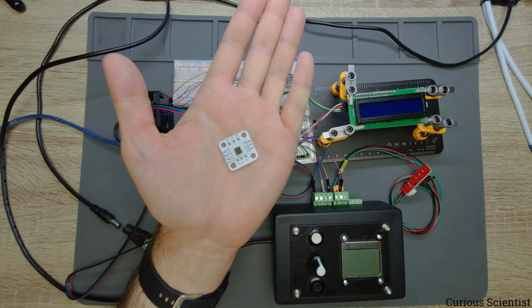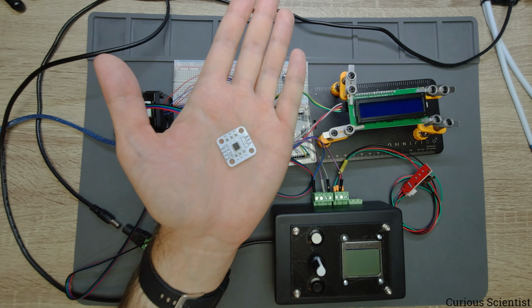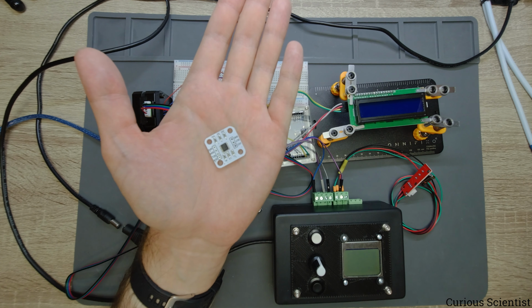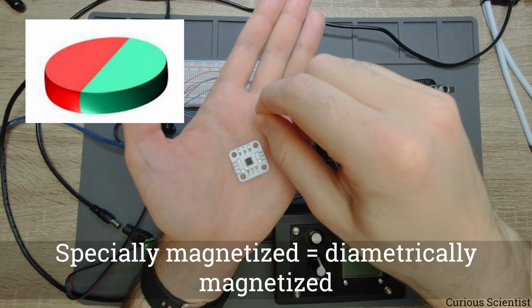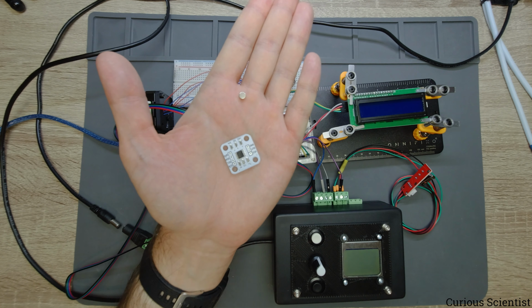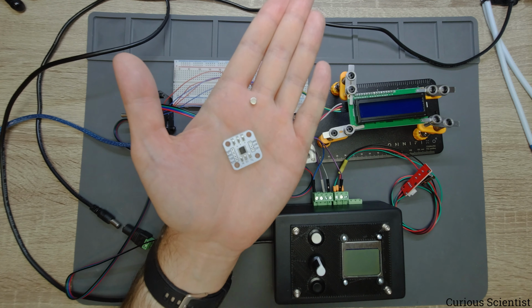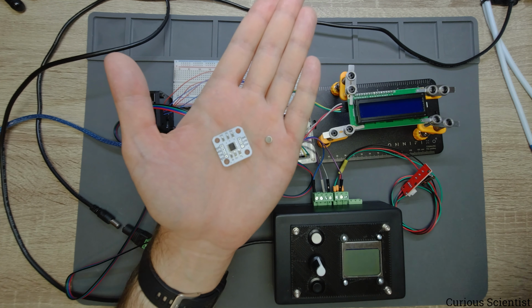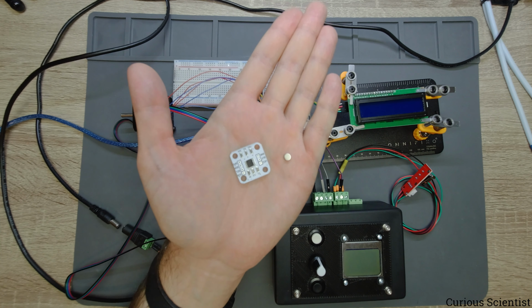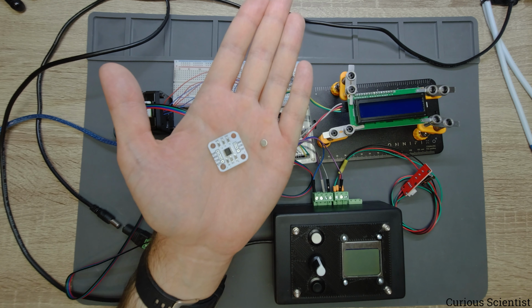We have a chip which contains several Hall sensors inside, and based on the displacement of a specially magnetized magnet, this small guy here, we can detect angular displacements, and then we can convert that into different kinds of parameters like speed or angular displacement and so on, anything which is related to rotation.